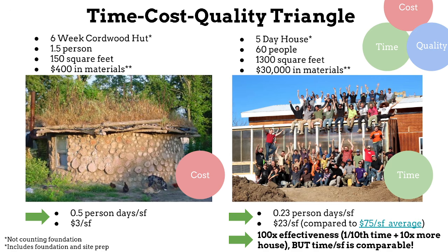Super low cost. Cost is low, that's a great advantage. It's super basic. You're just using dirt and twigs off the site to do it. For example, for the roof, we used black locust lumber, which is rot resistant and super hard, so it lives forever. Basically, carpet, polyethylene, and soil on top. It's dirt cheap.